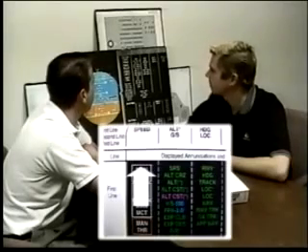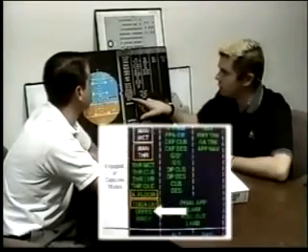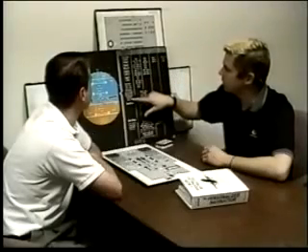Okay. Start with altitude cruise, altitude, and altitude constraint. What kind of autothrottle engagement mode would you have? Okay, they're basically the same. We're just trying to hold an altitude there, and we don't know what thrust that's going to take. Is it going to take climb thrust? Definitely not climb thrust to maintain it, unless we're at our maximum altitude. Is it going to take idle thrust? No. If we have idle thrust, we're coming down. So it needs some thrust in between there, and the only one of these that can give me that is speed mode. So all the altitude modes are associated with speed.